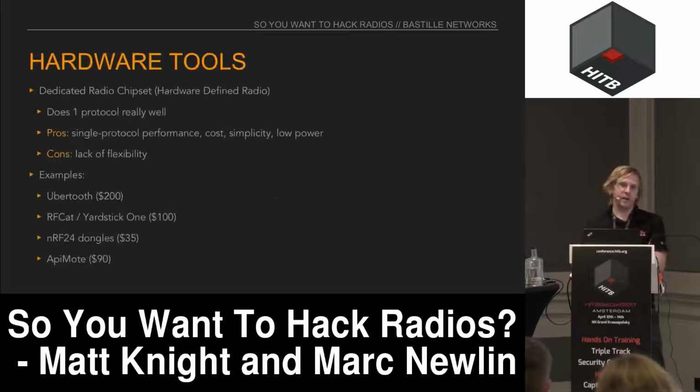On the radio side, we have the distinction between hardware-defined radio and software-defined radio. A hardware-defined radio would be something like the cellular modem in your phone or the Bluetooth radio in your laptop. It's an integrated circuit which is designed to do one protocol really well, but it's not good for a lot of reverse engineering processes because you can't configure it in the way that you need to look at an unknown protocol. We have some devices here for looking at Bluetooth and Nordic NRF24 and sub-gigahertz FSK protocols and Zigbee 802.15.4.